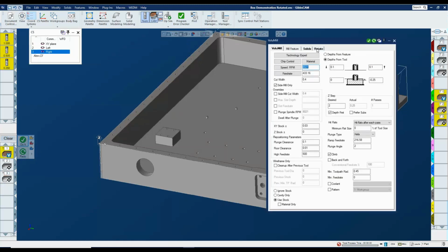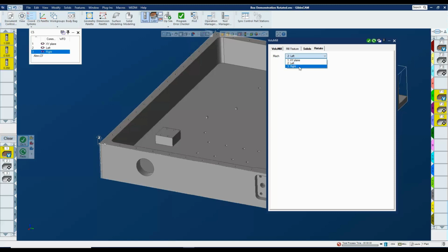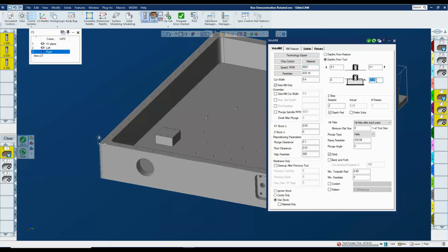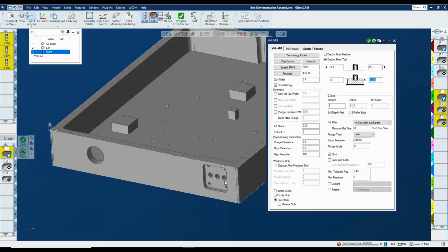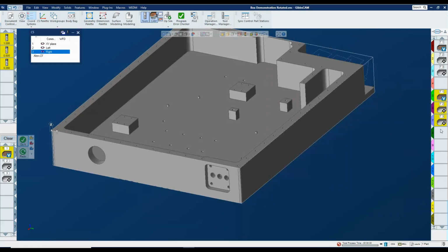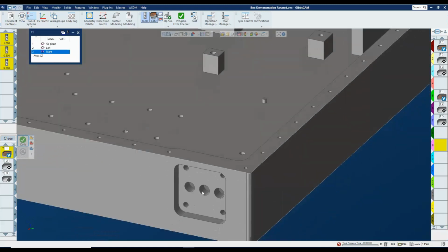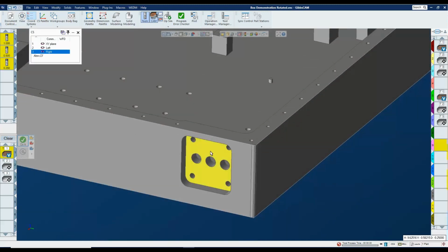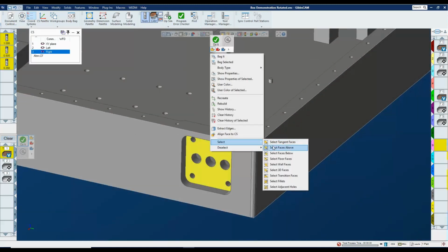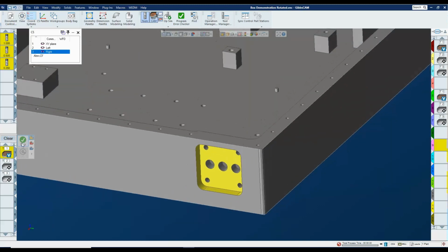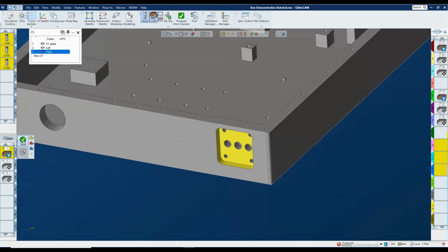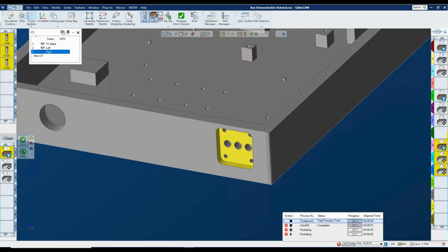And what we're going to do is activate the third coordinate system, and the same sort of thing. Make sure that the coordinate system matches, adjust our z values, which in this case, that's the same sort of pocket, so I really don't need to do that. And we should be good to go. After I pick the geometry, and again, same sort of philosophy, and now I'm going to say do it. Again, this should just take a few seconds to complete.